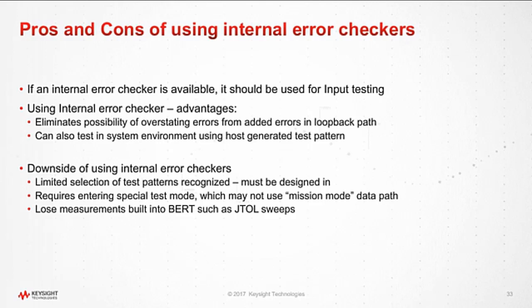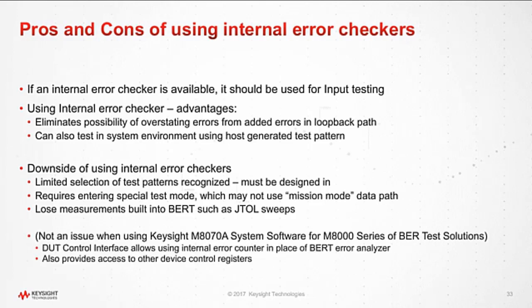As I said, if you're relying on the internal error checker, you don't have that capability with some BERTs, but now with our new BERT control software, we have this mode called the DUT control interface, and it allows you to access those internal error counters in your DUT through the management interface if it's a module, and then integrate that. Essentially it substitutes your error counter for our error detector. So all of the measurements such as jitter tolerance that are built into the BERT are accessible to you with this control. And it also is handy because it allows you to control other device registers once we have this interface in place. So it's just nice for troubleshooting in general.